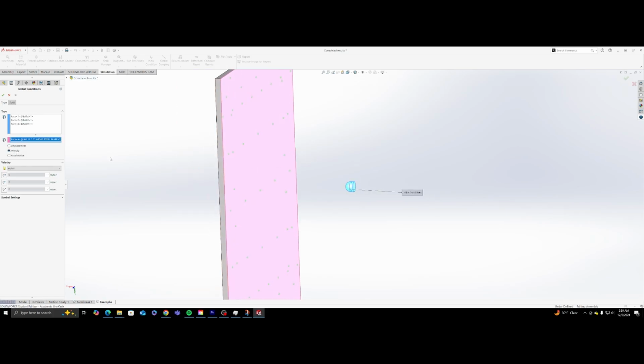And you are going to click that plate. And then you can click which way you want to move along each plane here. We are going to move this perpendicular to this back. Basically, the bullet is coming from the right, going to the left. Okay, and we are going to give this a speed of 500 meters per second.